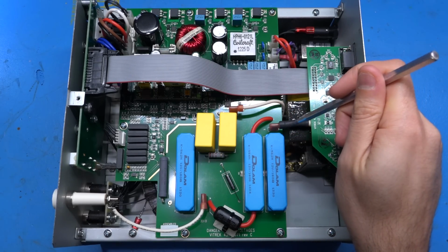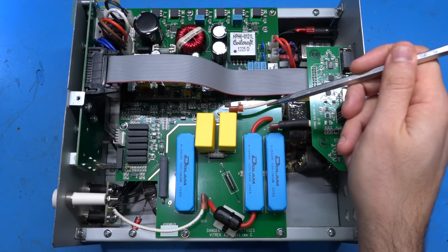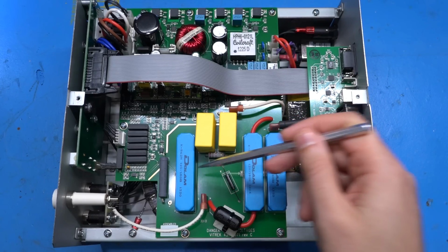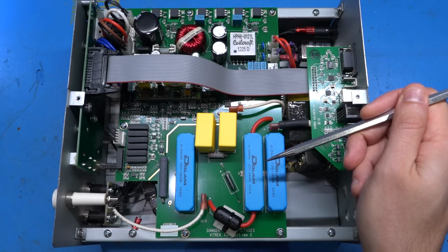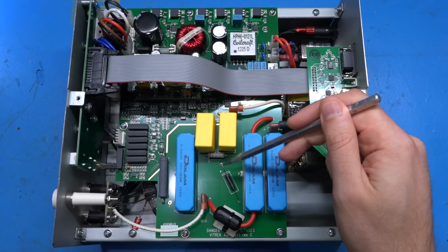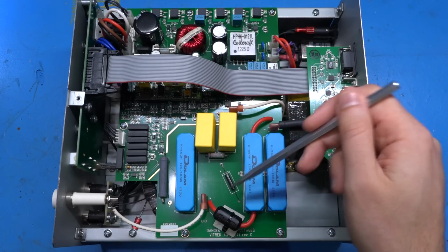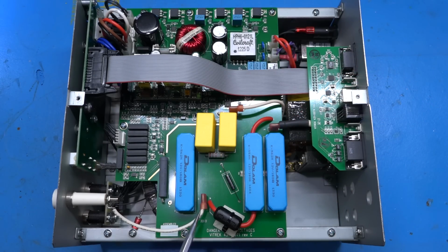It actually has two high voltage outputs, it looks like, and one of them might be used for the DC, one for the AC, or perhaps there are two different ranges of power coming out and the voltage coming out. And these big relays, these are 10 kilovolt relays used to switch between AC and DC, I believe. And then there is a 15,000 volt diode here, which looks like forming a very simple rectifier. So basically by switching that through, you get your DC voltage output. And this is the output of the main thing going over here to the main output of the instrument.